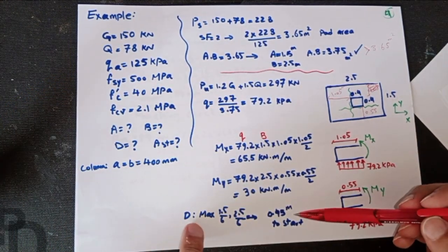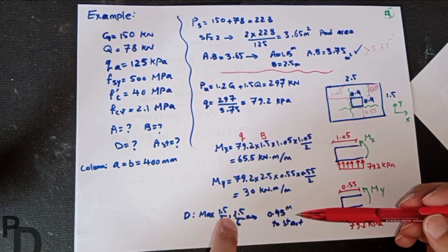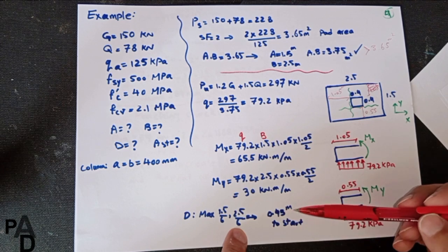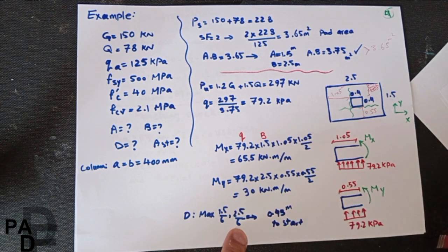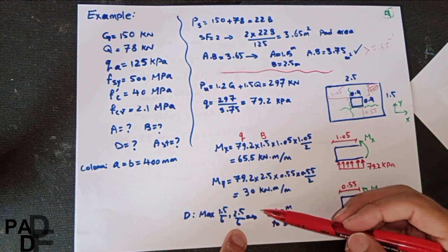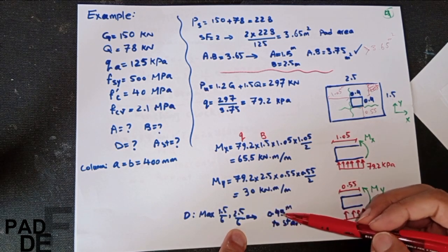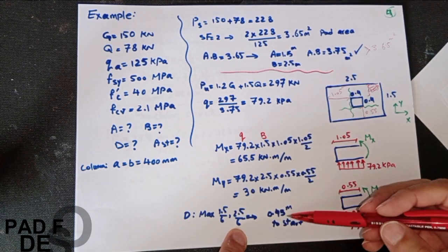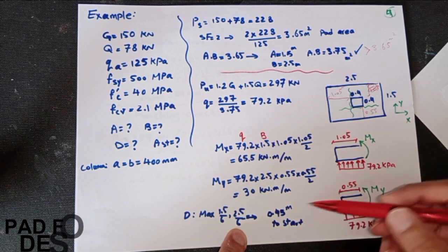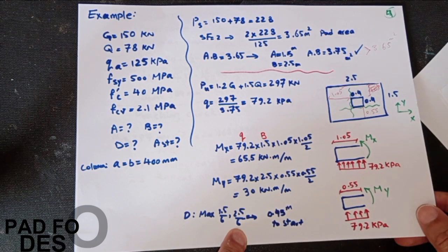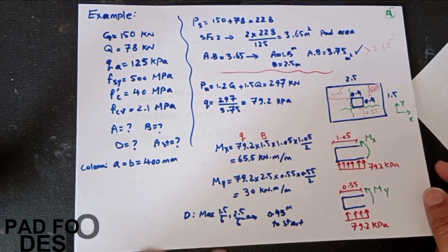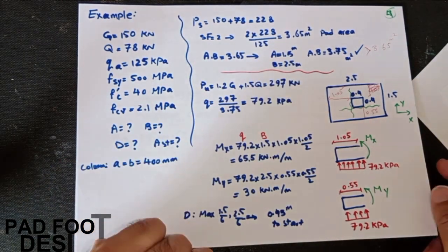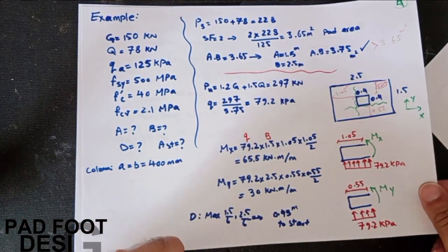So we're going to have maximum of 1.5 over 6 or 2.5 over 6, and it gives 0.545 meter to start. It should be 0.41, but just for safe design, or just to have less trial and error, we're going with a bigger number, that is 0.5, or even you can go with 0.5 meter. That is very common for pad footings. It still depends on the load value. Here we have big loads, 1.5 and 75 are quite big load for single pad.